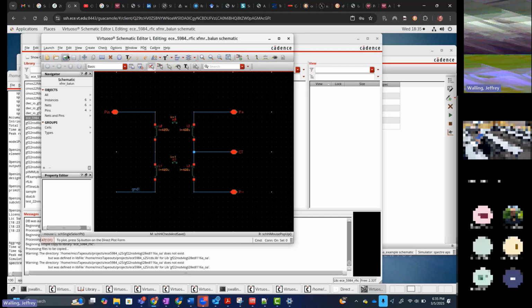Done. Yeah. Why do we need 2? I could, but then I don't have a place for a center tap. Okay. Yeah, so I'm making a balun now that I want to be able to pass DC through at some point. So what this allows me to do is if I had a DC bias that I wanted to pass to something, I could put the DC level right here, pass that in, that DC will be shorted right through these inductors, go to its target, but the AC signal will expressly be differential.